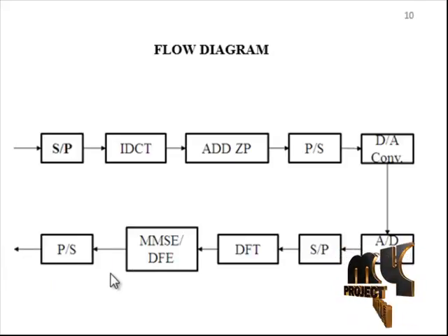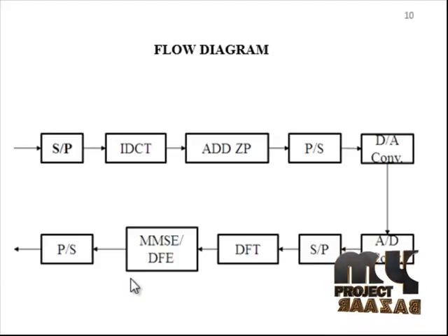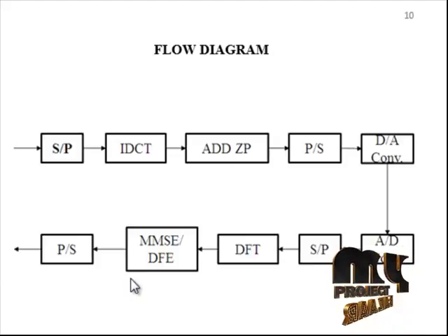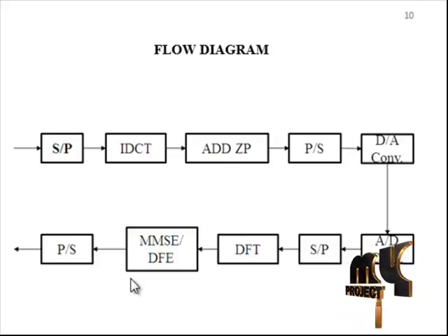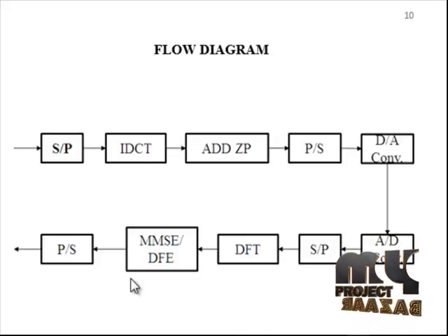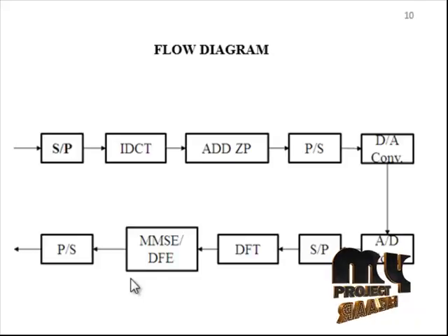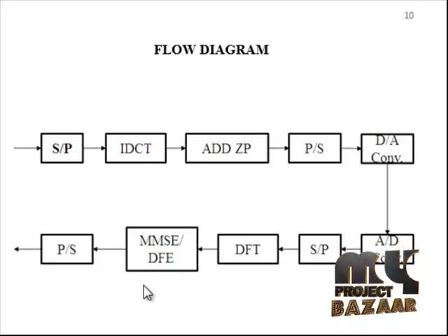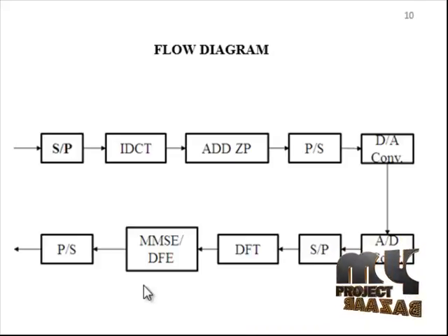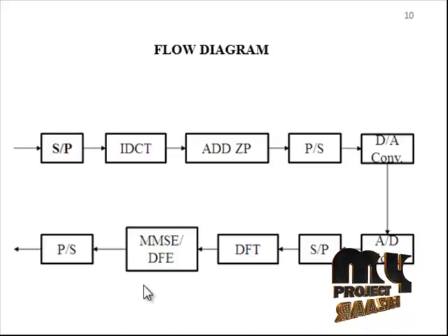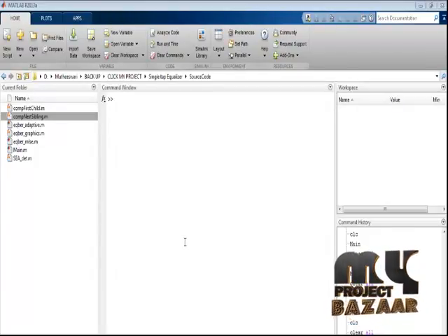Finally, the comparison graph will be produced, that is, the comparison of SNR between fast OFDM schemes and FDE based schemes. This system has some advantages for mobile wireless communication, as channels are robust against frequency selective fading. The performance of the proposed scheme is good at high SNR. It increases monotonically with increasing SNR, and with increasing delay spread the performance of the scheme deteriorated as compared to its performance in AWGN.